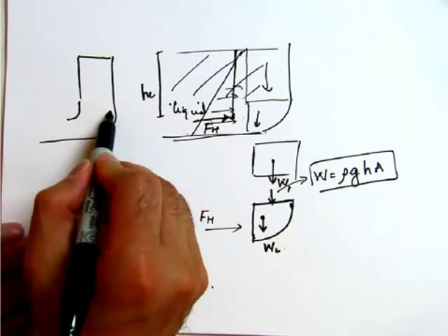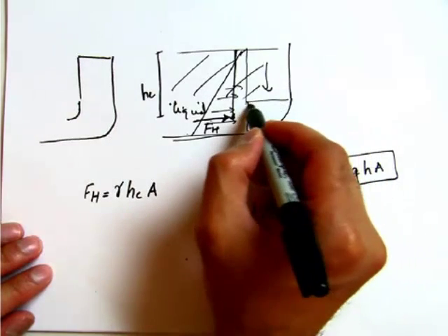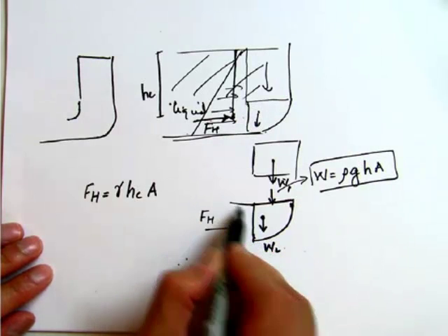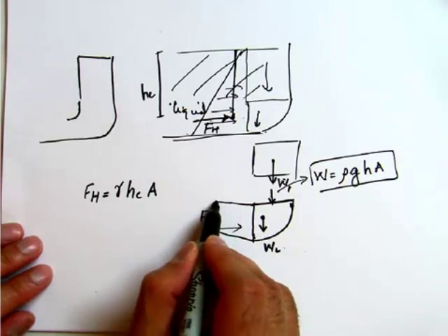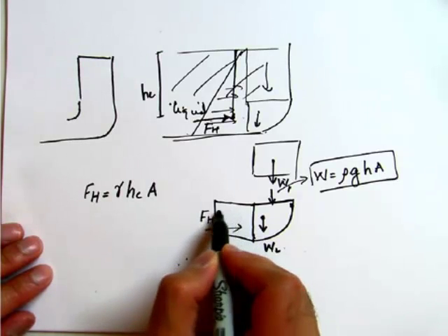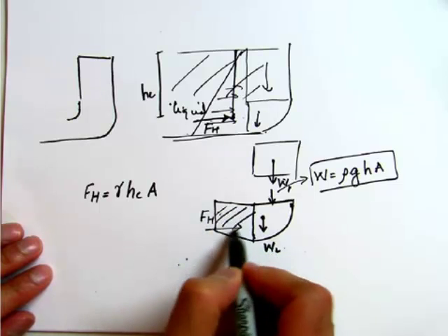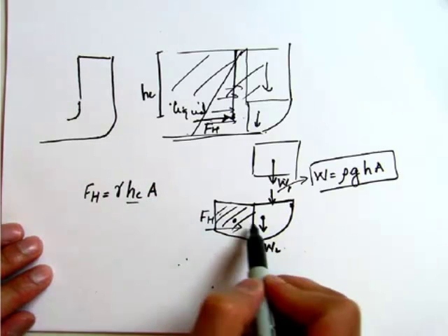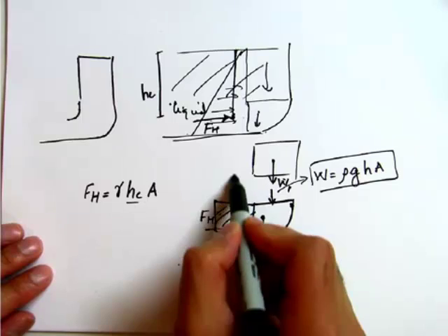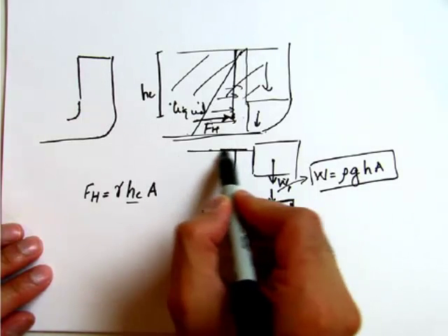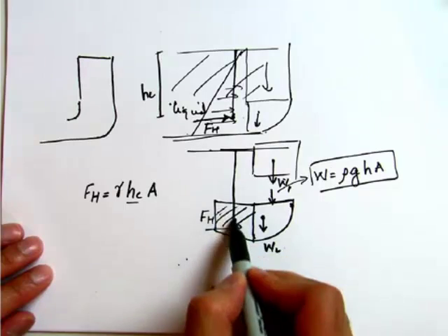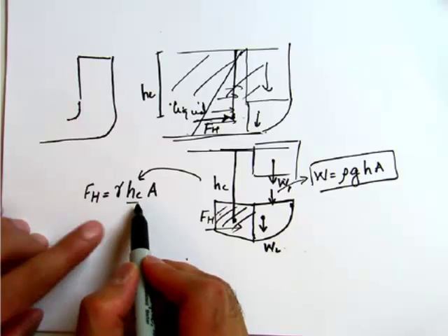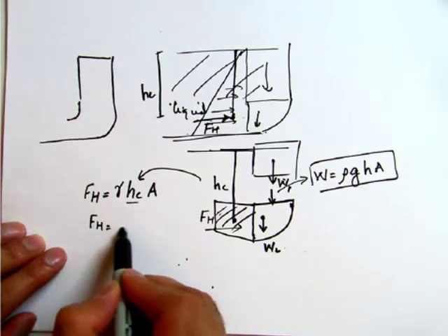This is not the best of pictures, but the idea is, if you think about this element over here, this fluid has some width, and this shape is a rectangular shape, and we are looking at the centroid of this shape. So that's the distance from the centroid to the top of the fluid layer. This is where the fluid is starting. So this distance is our hc. That is the distance you need to put in here to find your horizontal force.